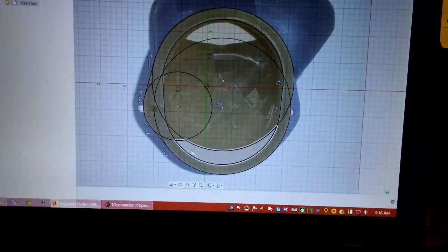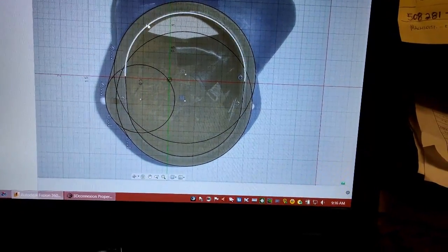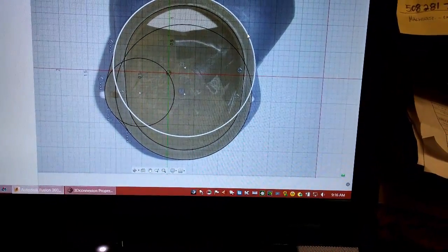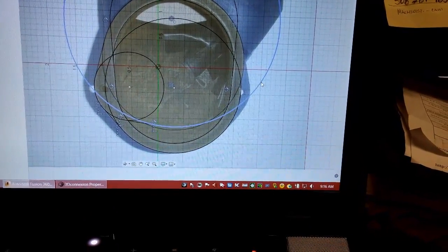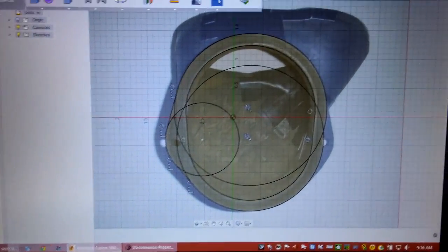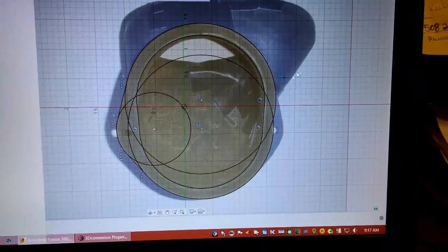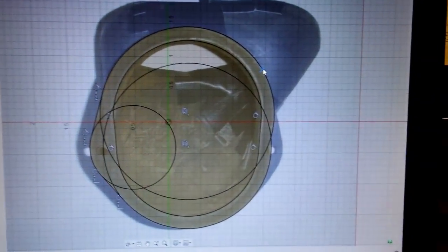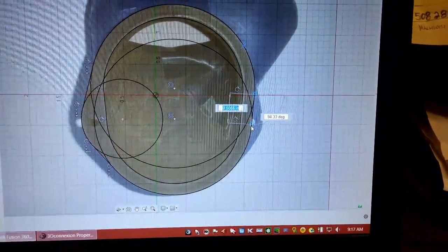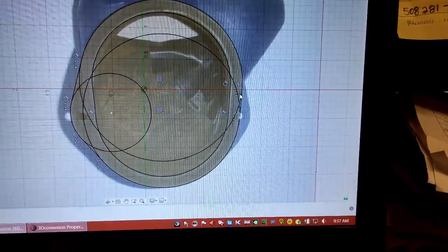I did the same thing down at the bottom. Then you take a line, and you click and hold, and it'll create a, let's Control Z that. I need to select Line first. Okay, so this should put me at drawing a line. So when you come on the edge there, if you click and hold, it'll track around and stay tangent. Then you can find the point over here where it's tangent as well. And that's how you get your connection lines there.